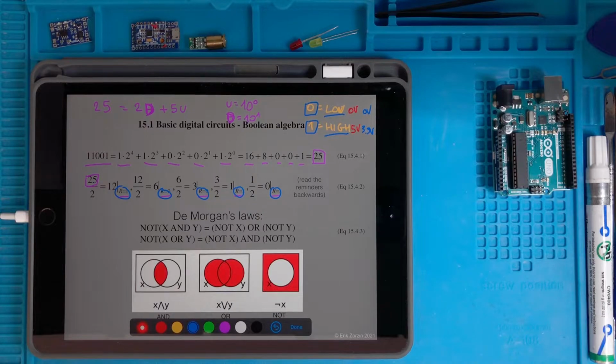But they quickly understood they had problems related to noise. If you want to represent very big numbers, then at a certain point you need an enormous number of voltage levels, and you can imagine that if your range of voltage is limited because of the power supply of the amplifiers involved, then the delta V, the difference of voltage between one level and another, becomes so small that a little bit of noise present in the environment will easily corrupt the digits.